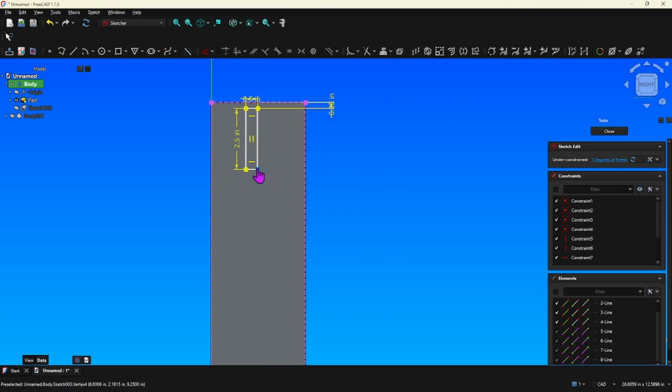It slides left and right. Now we just need to center it on that post. Let me grab this dimension. We have a 4x4 post, so it's 2 inches from here over to the center, which means another 1/4 inch in either direction would put this line here. It would center this slot.